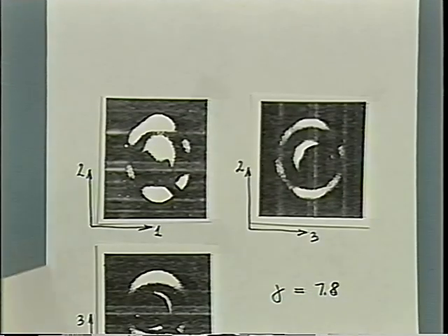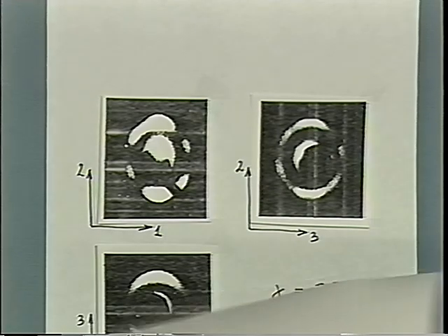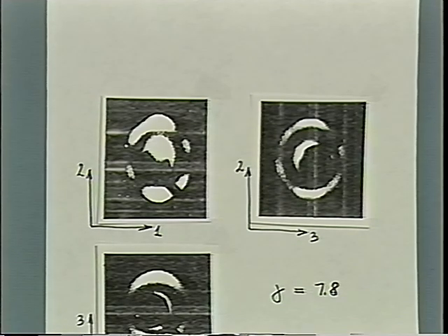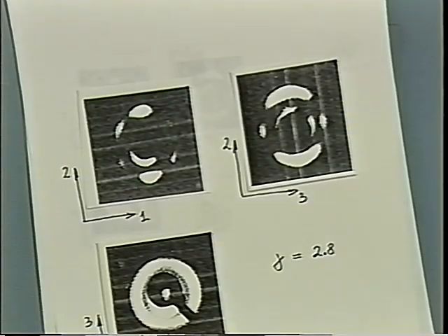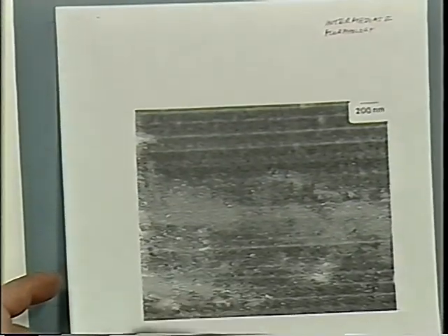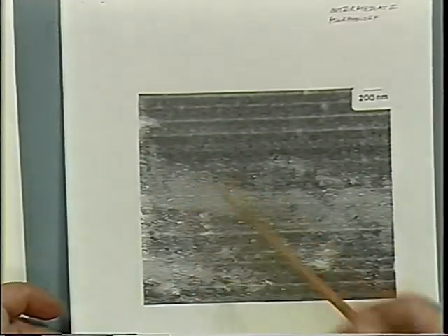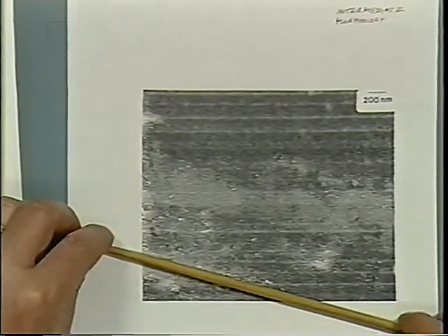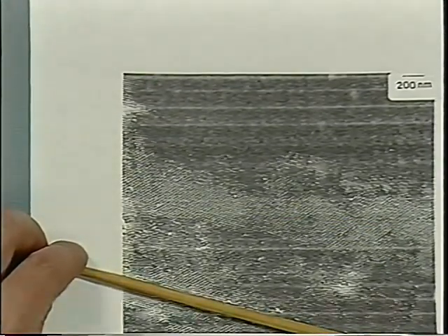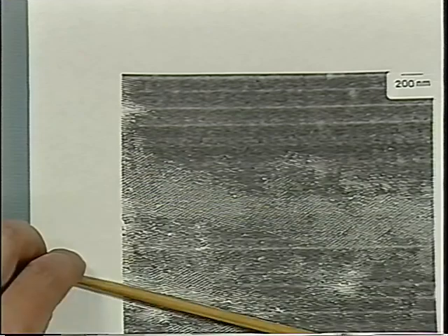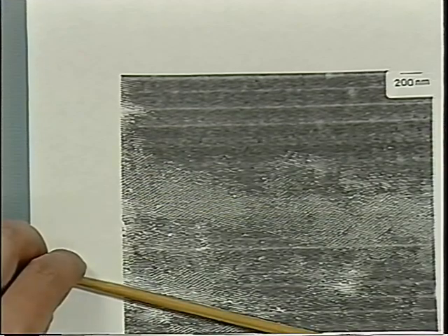But I want to mention this intermediate structure also at, say, 2.8 shear units before moving on. We somehow get some ordering, and when looking at the microtome of that structure, now this is hardly visible at all. It shows that there's some alignment, and then there's an alignment by 90 degrees. So the vector has changed very rapidly for some region in the material.